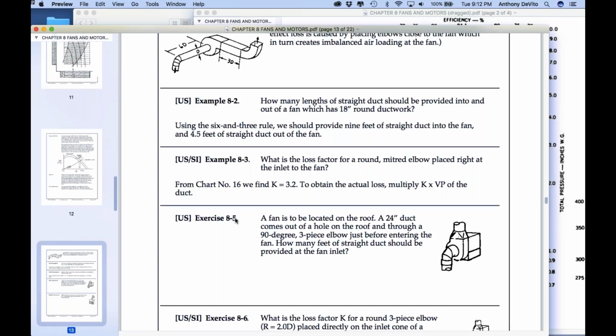So I mean, you could maybe manufacture some sort of hood, if it's jackhammering here, that you can make out of plywood or something like that. It is right by where he's jackhammering, so you can suck air away. We're going to set up similar to how they do for asbestos.